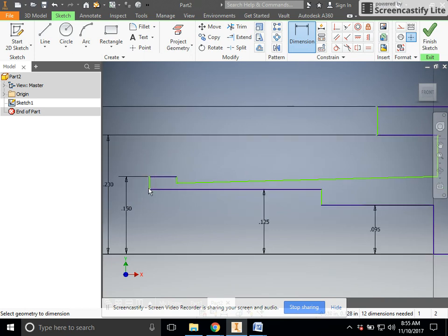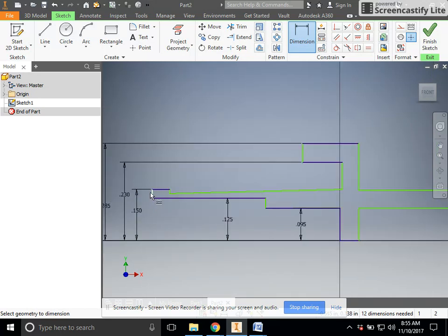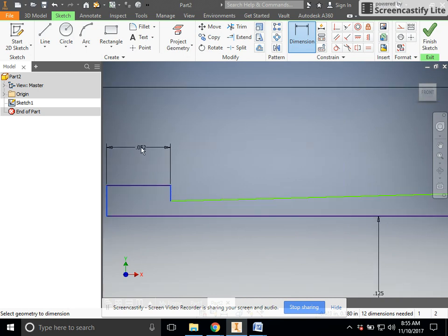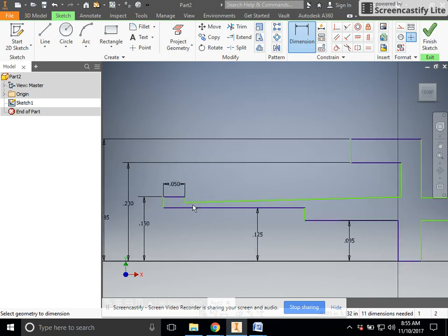And this year, the good part about the new schematics is they are using datum dimensioning, and all starting from the one side over here. A lot better than it was before. The first one is 0.05. The next one is 0.20, but that one is in reference to the slot that we're going to cut through this later. So we're going to skip over the 0.20 and go to 0.25, which is from this point to this point.